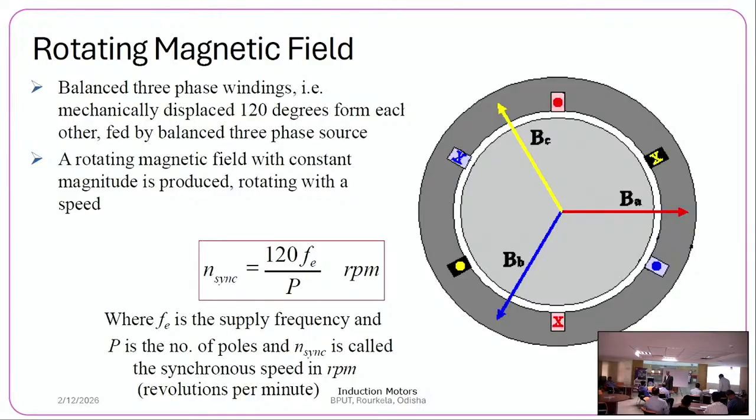In the DC machine, the armature is on the rotor, and the stator carries the field poles and field winding. So their field is stationary, of constant amplitude and steady, not a rotating field. And because the armature is rotating, because of the relative speed between the stationary field and the rotating conductor, an EMF is induced.